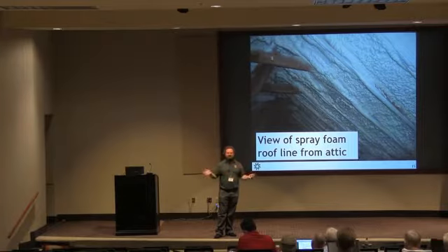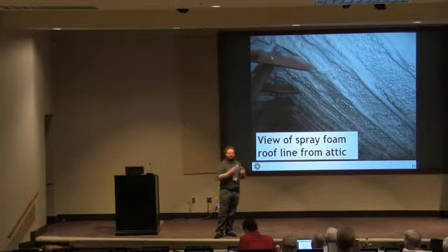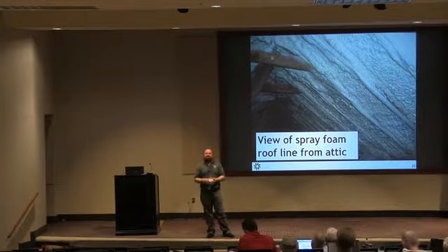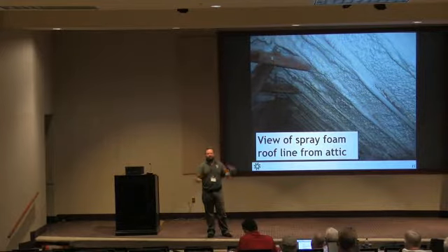If you've got an existing 10-year-old roof and then you're going to go foam underneath it, if you degrade 1% of the shingle life, okay, I'm going to re-roof a couple months earlier. The impact is largely overstated when you look at the building science of it, and it really comes down to, I make fiberglass and roof shingles, I don't want to warranty spray foam with my shingles. Find a manufacturer that manufactures both, they'll warranty an unvented assembly.